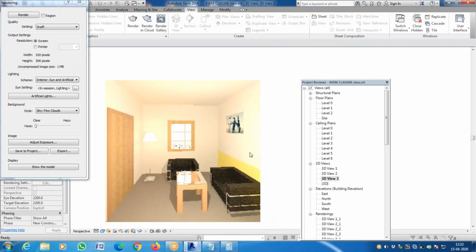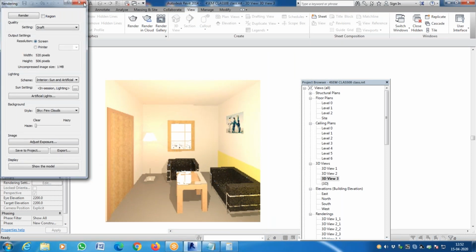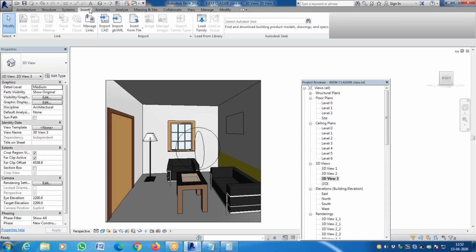This is also important when you're showing interiors. So you need to add some picture somewhere. You can add it using insert and go to 3D. Always work in 3D. Insert decal. Decal is right here. You can select that and create a name for whatever you're doing, so that when you have many pictures, you don't get confused. You will find it all there.